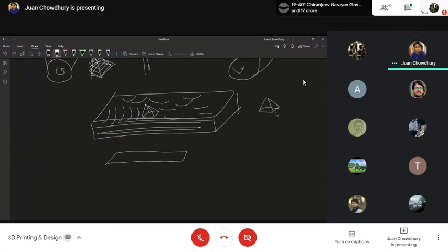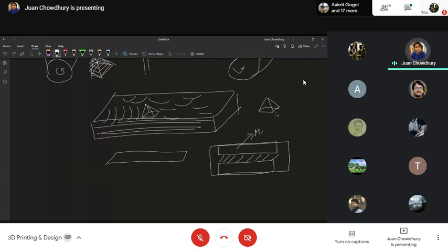This increases the flexibility of building composites immensely, because with a laser, not only can you cut the sheet, you can also melt some adhesives embedded in a sheet with a certain amount of heat. Consider this as one single sheet. That's material number 1. That's material number 2. And we have adhesives over here.